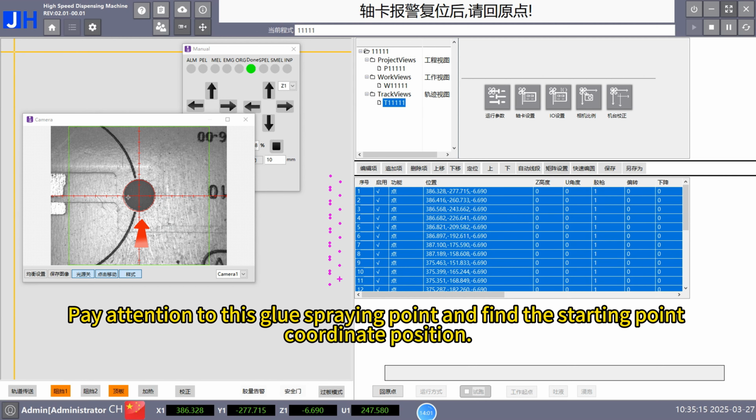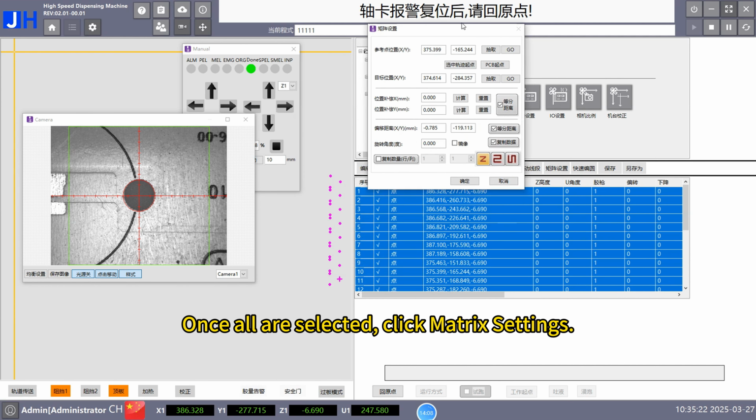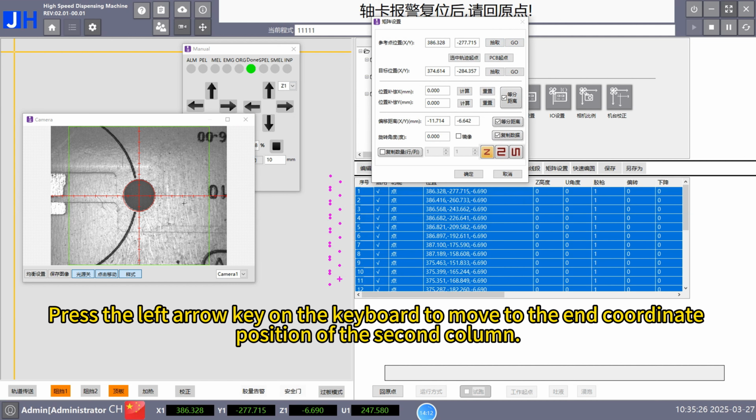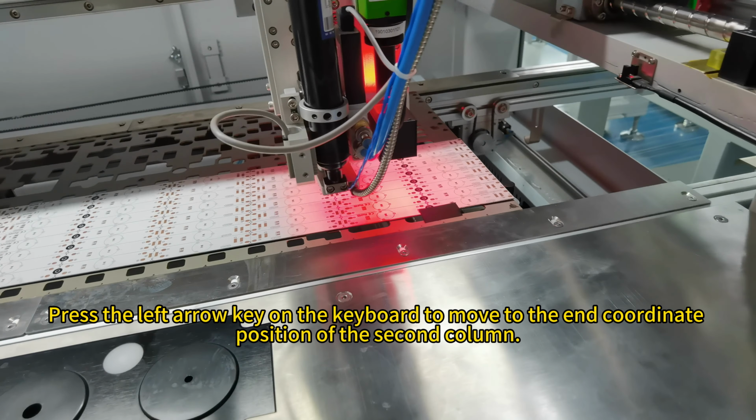Pay attention to this glue spraying point and find the starting point coordinate position. Once all are selected, click Matrix Settings. Click to pick the current starting point coordinates. Press the left arrow key on the keyboard to move to the end coordinate position of the second column.